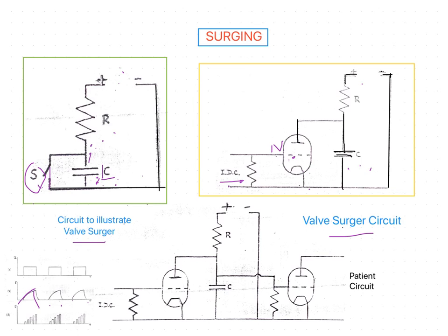Then the valve becomes capable of conducting a current, and the condenser discharges across the valve. This is a circuit of low resistance, and the discharge is rapid, so the potential difference between the condenser plates falls quickly. Thus the condenser charges during each period of flow of the interrupted DC and discharges when the current ceases. This is what happens.